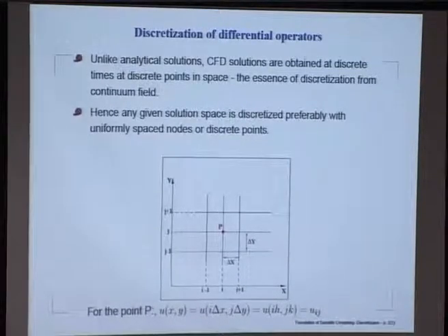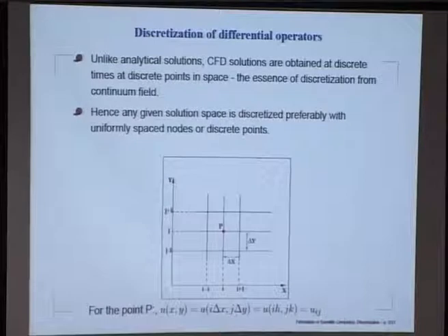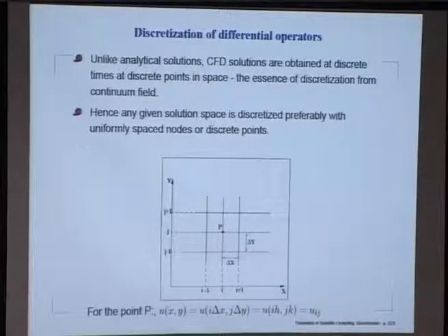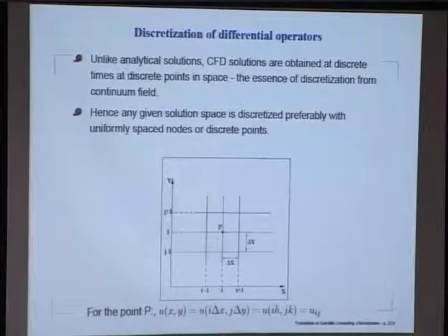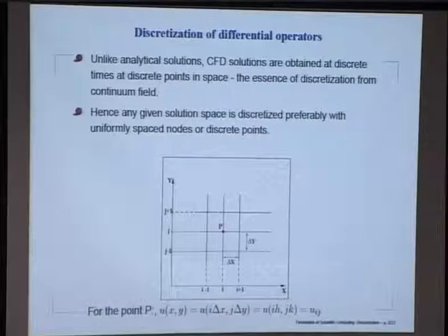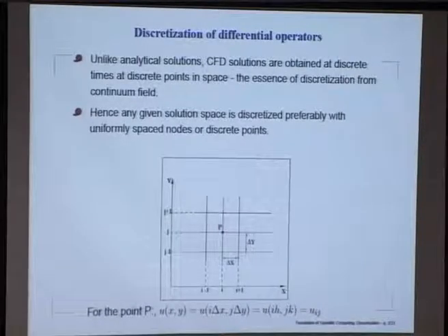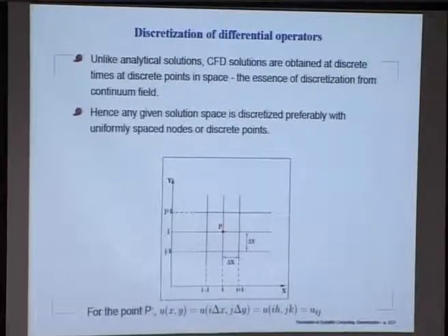Well, I have shown here what is called a structured grid, where the lines are drawn with a very good structure in mind. People also use unstructured grids. We will not do that, because structured grid analysis has gone light years ahead of unstructured grid methodologies and analysis. So, we will keep our attention focused on structured grids and try to find out what discretization brings to the table.